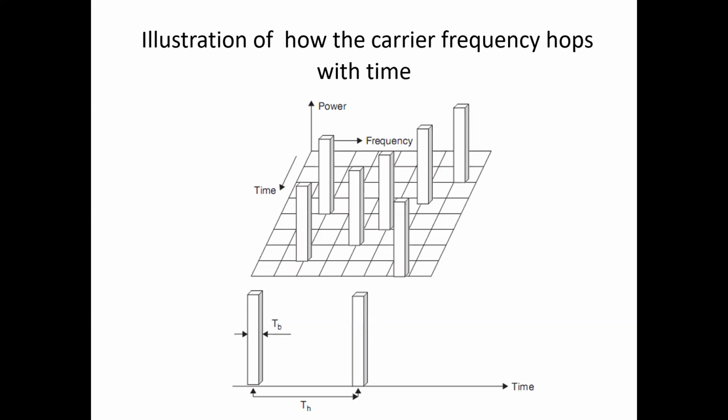Now, in the direct sequence spread spectrum, if you are going to recover the original signal, we need the chip code in order to despread the information signal and recover the m of t. In the frequency hopping spread spectrum system, the location of the carrier will be determined according to the chip code c of t.